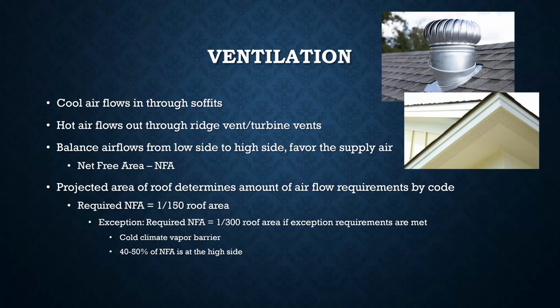If the air is in your attic longer, it's going to heat up more or cool down more, and it potentially might have more vapor problems. So in a cold climate where it's a problem, by putting the vapor barrier in, you're basically negating any impact of lesser ventilation. So that's sort of a reason.